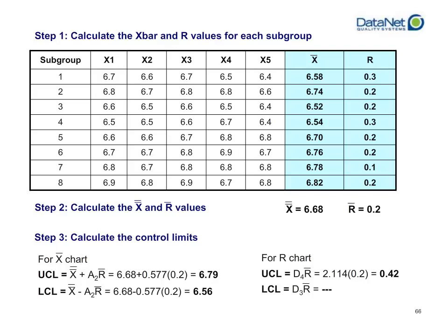If you had a lower control limit, which in this case there actually isn't one that is applicable, you would multiply your D3 value times your R bar. In this case, it doesn't actually have a meaning, there's no valid lookup for that, so you're not going to get a value. It's undefined. Another thing to keep in mind is just a quick sanity check. Your range is a magnitude. It is how big your largest from your smallest values are. You should never get negative values. You should never be able to get a value that is below 0.